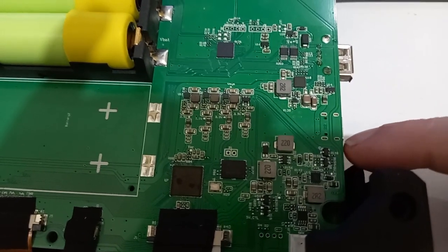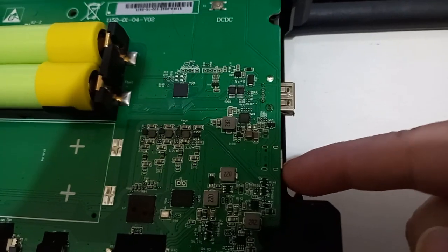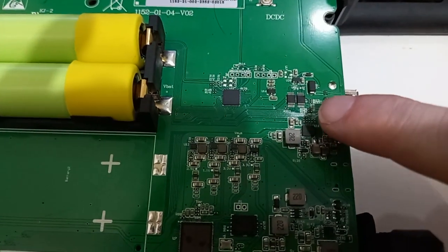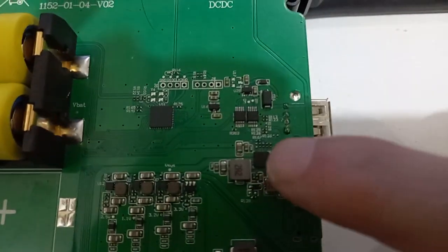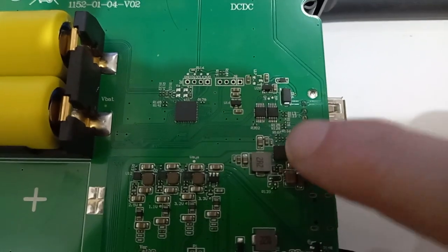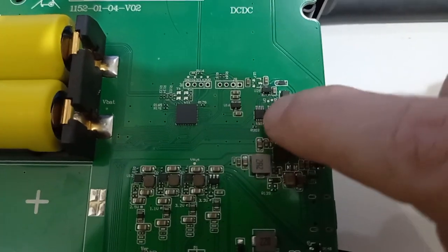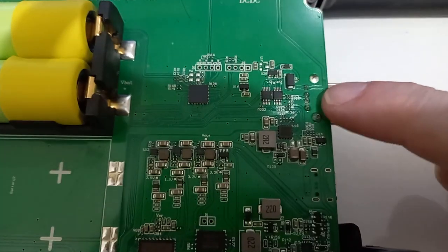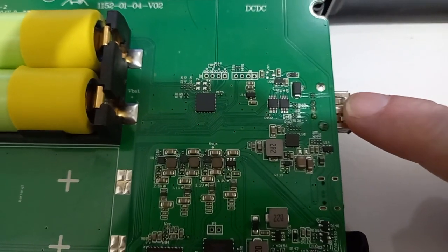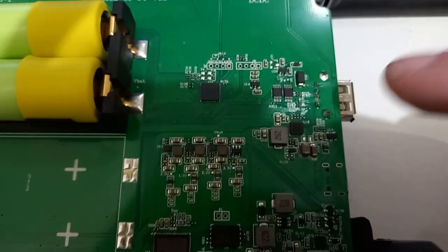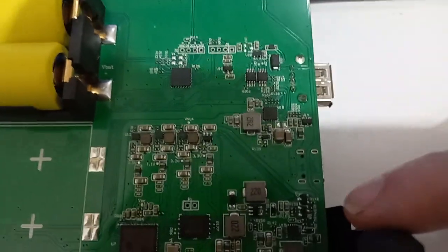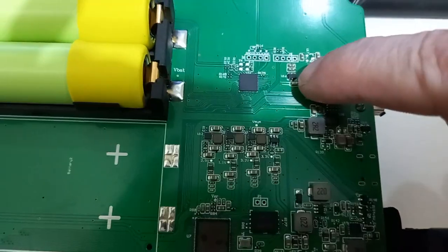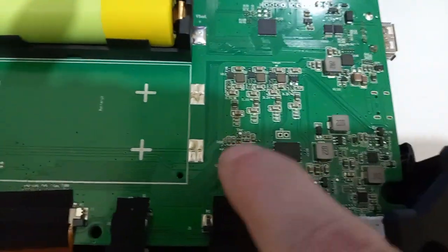But when you plug the cable here, this chip senses the presence of the cable, and then it gives the signal to the two switches here, and basically the flash drive is disconnected from the line. Instead, the main port through this switch goes back here again.